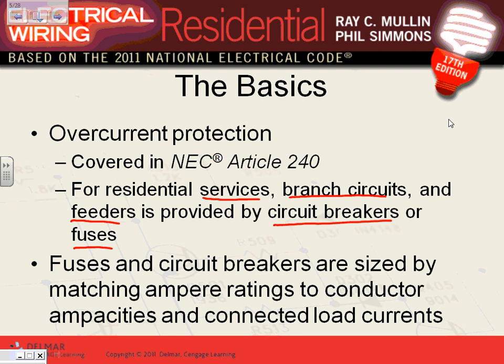So we talked about, guys, the 3 very important circuits in any electrical system. We said the service conductors, the feeder conductors, and the branch circuit conductors must be protected at the point where they receive the power, the juice. At the point that they receive the juice, with some exceptions, they must be protected by an overcurrent protection device that limits 2 things.